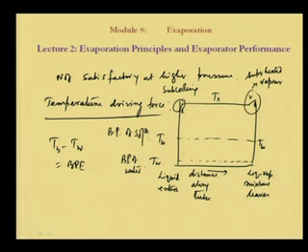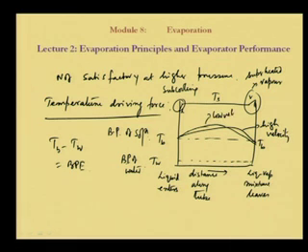as it goes along the tube, there is a profile like this, and there is another profile like this. This is, say, for high velocity, and this is the low velocity case. This is case A and this is case B. What is happening is that this is the boiling point of the liquid, but the actual temperature happens to be like this for the low velocity situation.